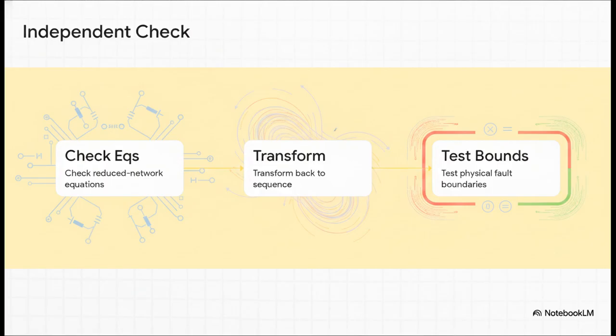Just remember, an answer that merely passes the formula used to compute it hasn't actually passed a true independent check yet. Always compare fault types on the exact same base, at the same bus, with the identical pre-fault state and declared network model. Consistency is everything here.